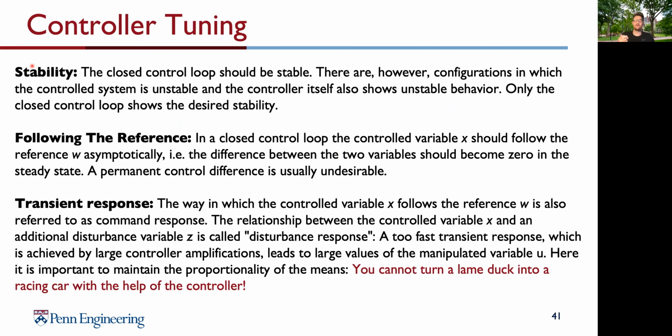So again, why are we doing this? Because we want to tune our controller. We want to figure out the individual parameters for our control gains, Kp, Ki, and Kd. And we can analyze our system regarding stability. Again, the system is said to be stable if its output is under control. Otherwise, it's said to be unstable. A stable system produces a bounded output for a given bounded input. So it's not the case that our output is getting bigger and bigger and bigger.